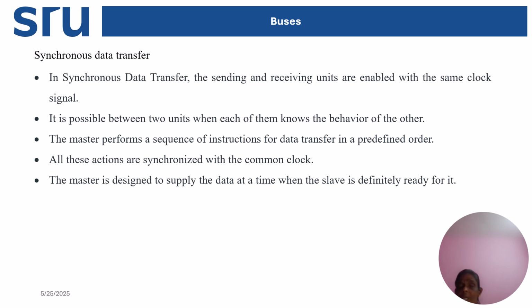That is why from the main clock tree it has to supply both the devices, because the features and characteristics should be the same. Both clock signals should be identical. That is why both the receiver and sender should take the clock signal from the same clock tree, not a separate signal, even if the clock rate is the same.